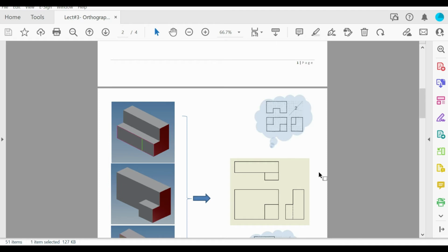Actually, it is not a cut. Now, if it is a cut, that means there is a line here, and what we have in the front view and in the side view, the original one, as you see here, there is no solid line here. That means we don't have a line here or cut. It should be something called join, not cut. So we have material here, as you see. The cut is behind, not in the front.